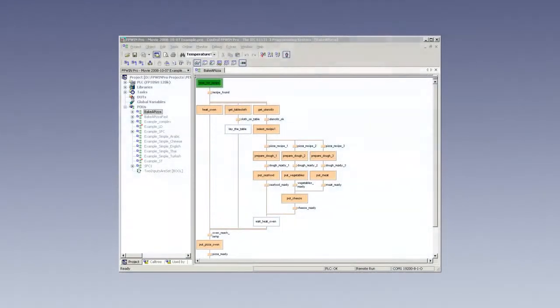Sequential function chart, SFC, allows you to combine several program elements created with any IEC programming language into one overall program. Hence, SFC provides you with an excellent overview of even the most complex programs. Monitoring illustrates which program step is currently active in different colors. If a problem occurs, simply debug the affected subprogram.